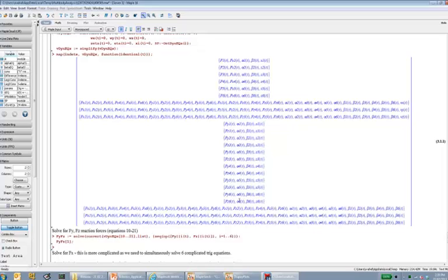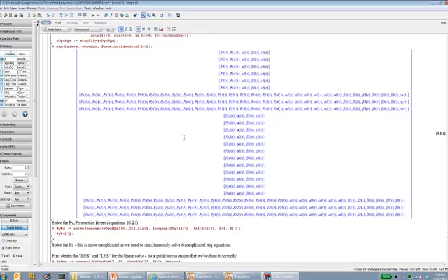So these are known, since we have the inverse kinematic solution. We can use these equations to quickly find Fy1 and Fz1. Once those are known, we can use the remaining 6 equations to find the Fx's, which are the forces exerted by the actuator in a prismatic joint.